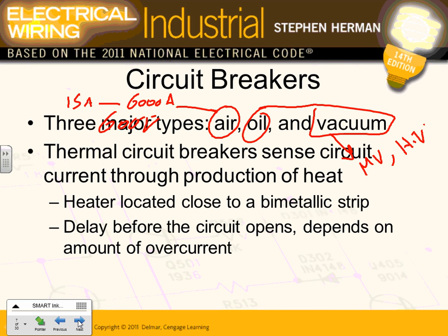So the types, the structure, is 3 types. Then the sensing mechanism is also, guys, 2 or 3 types, how they sense to trip. Thermomagnetic. Thermal, remember that thermal, it expands 2 dissimilar materials, expands at different rates, it trips the circuit breakers, that's a thermal. The magnetic, a coil, you energize a coil, a short circuit happens, and bam, it literally pushes a contact to open.